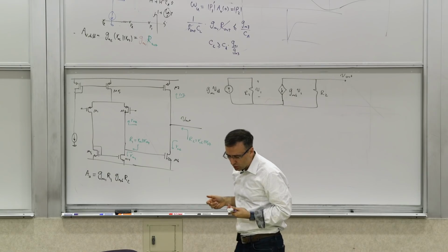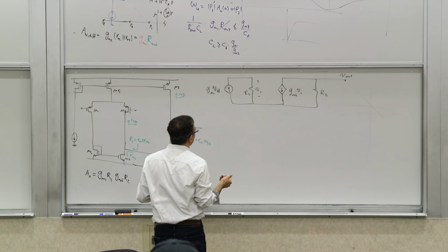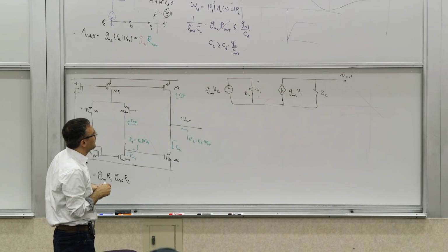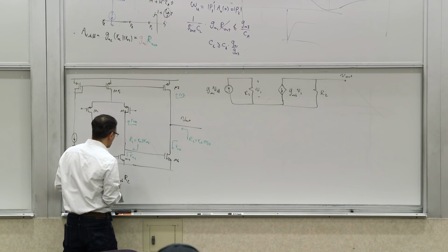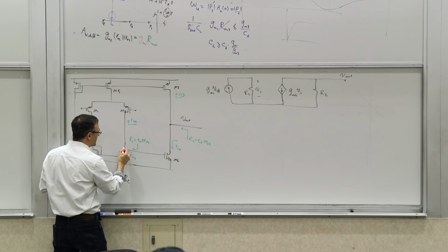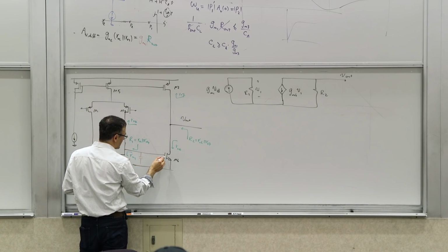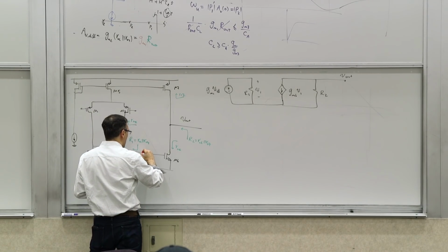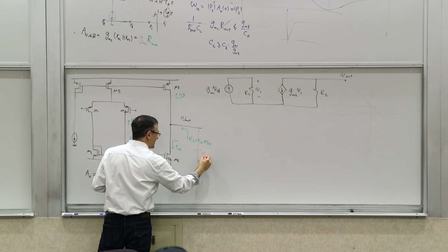So this is the way it looks from an equivalent circuit for the differential input. Now, what you can see here is, what are the capacitors of concern? You have the capacitance on this node, which comes from a combination of the capacitance of these devices plus the input capacitance of this guy, CGS. Let's call this C1. There is also the load capacitor, CL.